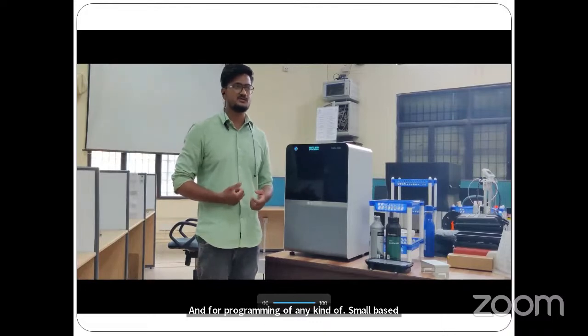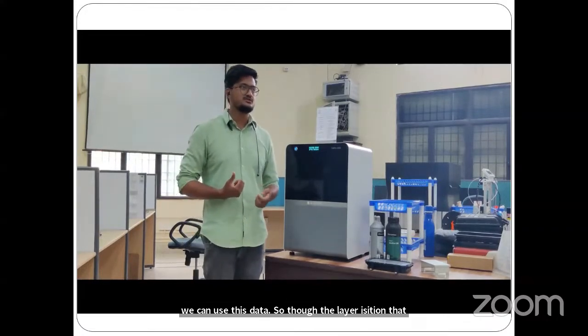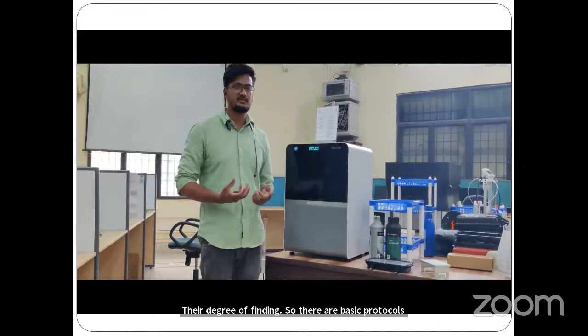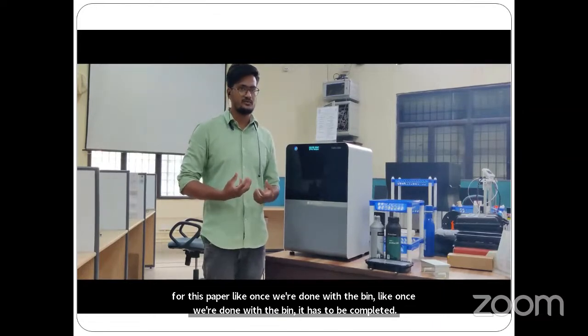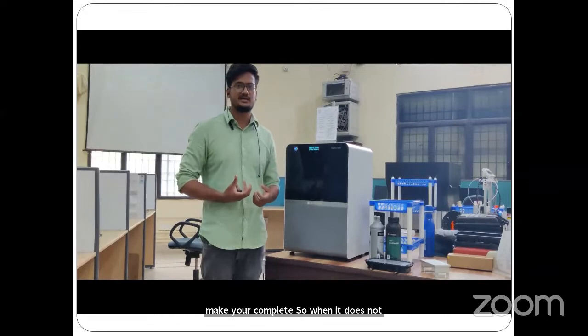Based on that, we can use this printer. The layer resolution that we can achieve is 30 microns to 100 microns. That is very fine and accurate. There are basic protocols for this print. Once we are done with the print, it has to be completely cured. That means we have to expose the part with UV light so that it can be cured completely. When it is not cured, you won't get the mechanical properties of that part.